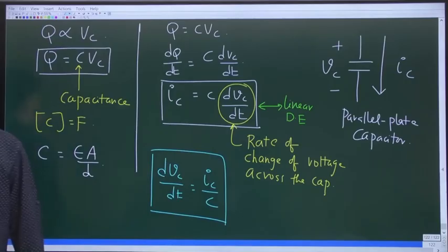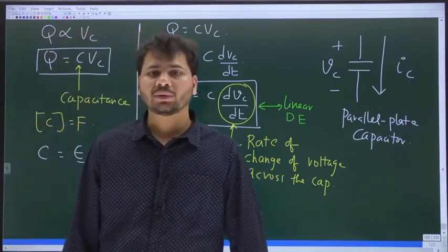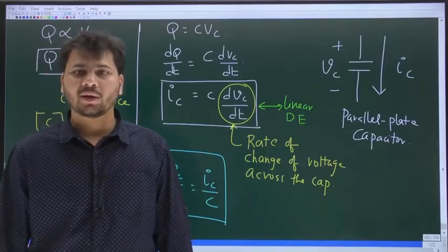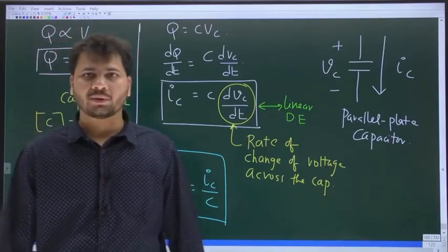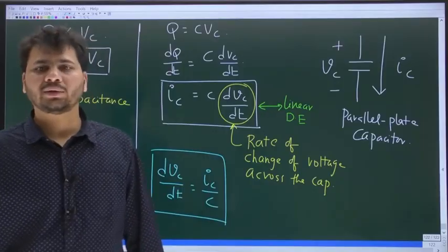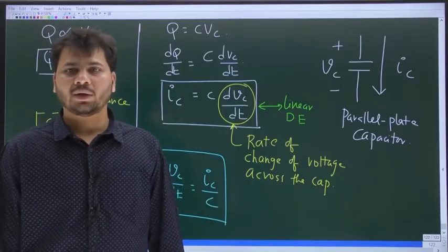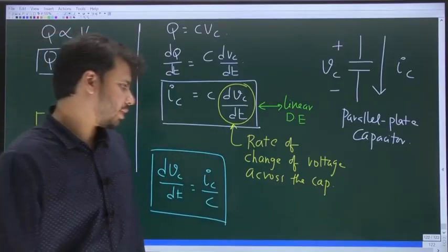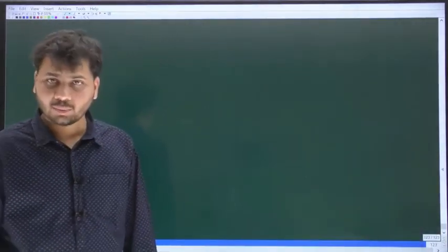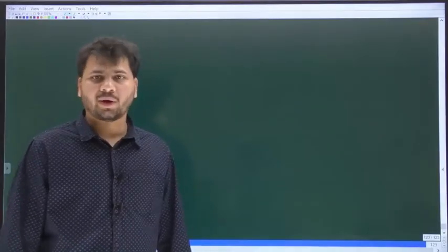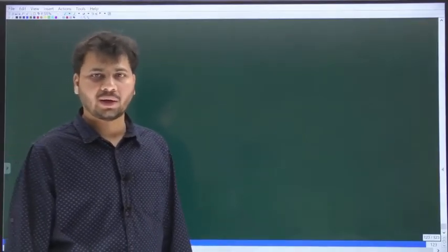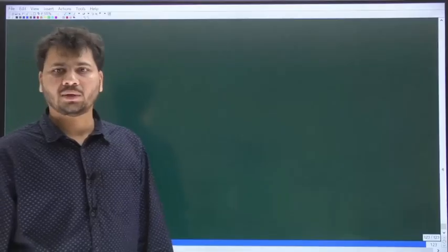Superposition. Very good. Yes or no? Just by checking whether superposition is satisfied or not, we can decide if any given system is linear or non-linear. Okay. So let us apply the superposition test to determine whether the capacitor is linear or non-linear.